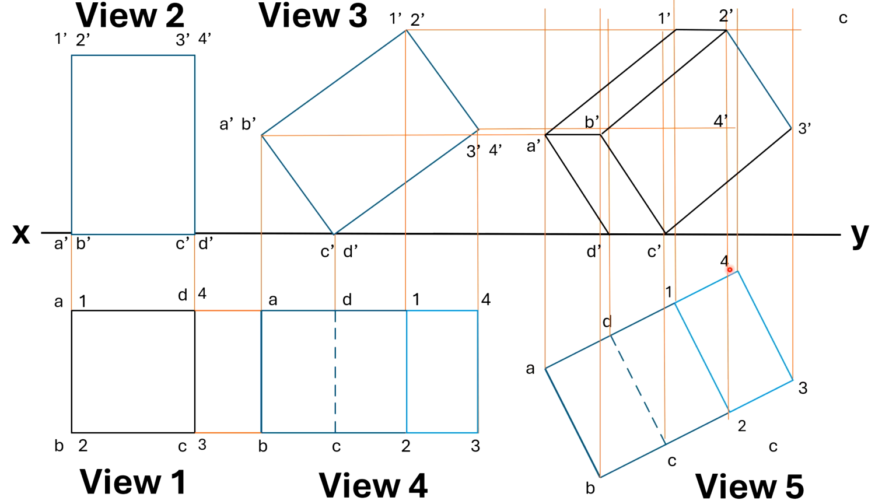3 to 4 is above this line, D to 4 is above this line, and likewise 1 to 4 is also above this line. So you can make 1 to 4 also a hidden line, and 4 to D also a hidden line. It is not visible.